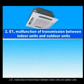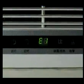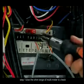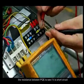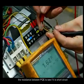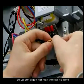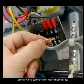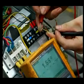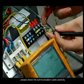2. E1, malfunction of transmission between indoor units and outdoor units. Repair instructions when E1 appears. Step 1. Use the OHM range of the multimeter to check the resistance between PQE to see if it is short circuit, or short connect PQE on the other side, and use the OHM range of the multimeter to check if it is closed, to confirm if the communication cable is broken or not. If short circuit or open circuit happened, please check the communication cable carefully.